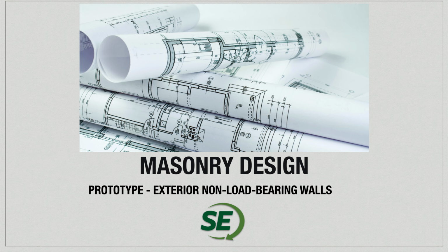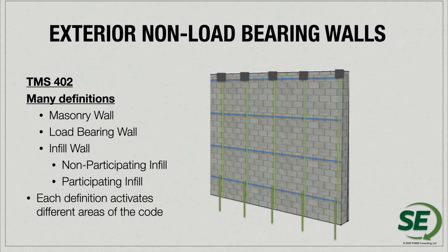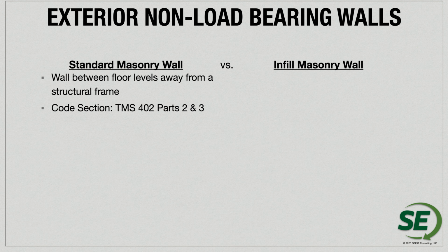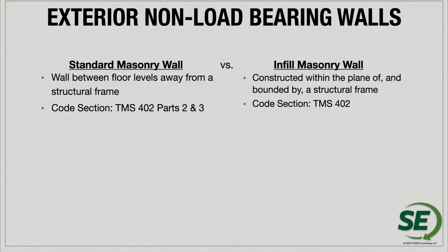In a very similar fashion, we have exterior non-load bearing walls that we can really treat in a very similar way. We have masonry walls, we have load bearing walls, we have these infill walls, which can be participating or non-participating elements within design. So if it's an exterior non-load bearing wall, if it's a standard masonry wall, then we have a wall between floors away from the structural frame, following certain code sections. If it's an infill wall, it's going to be constructed within the frame, bounded by the actual structural frame.